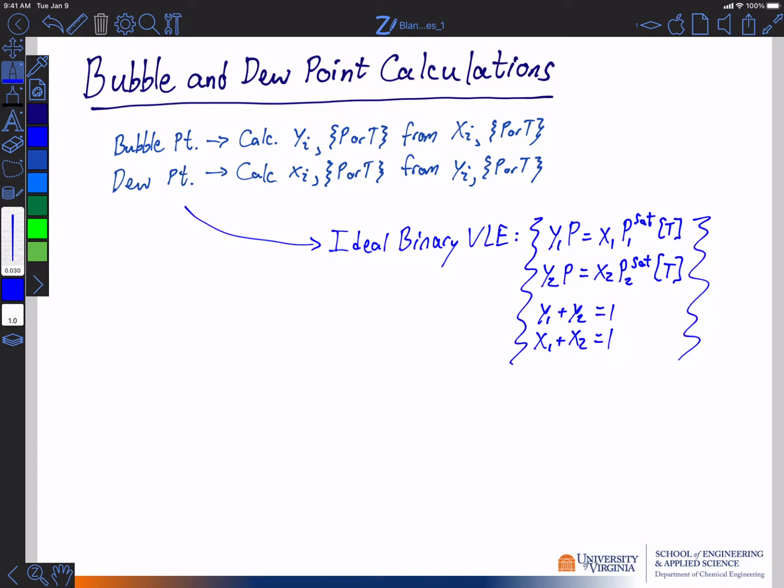So we'll remember, and it's important to keep in mind, right, that these K values defined for a particular component are functions of temperature and pressure, right? So if we go and look through Wankat, for example, equation 2-28 gives us an expression for the K values in terms of temperature and pressure. The de Priester charts give us that information. But we need to keep in mind that K depends on T and P, right? And so that's going to be very important in terms of doing these calculations.